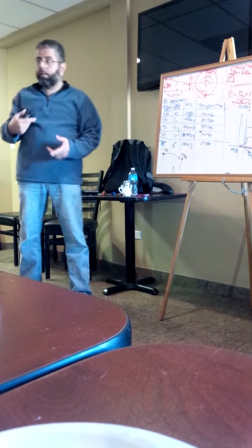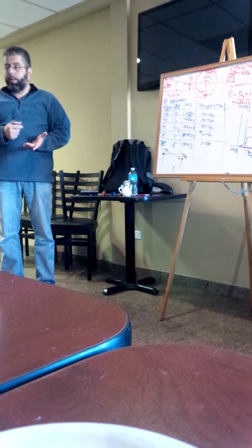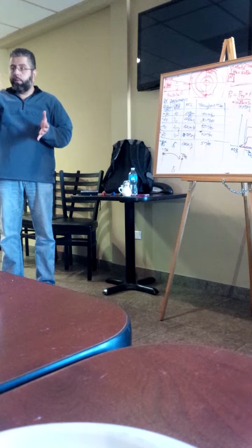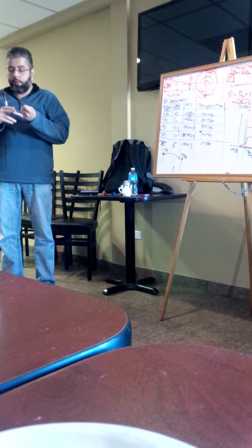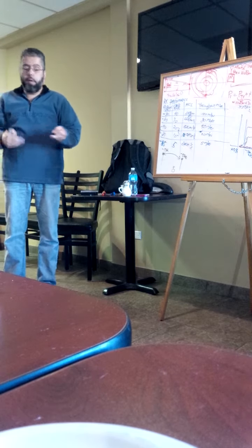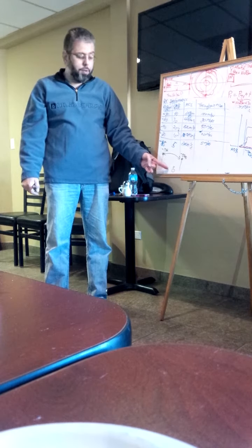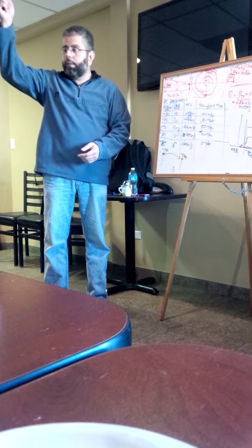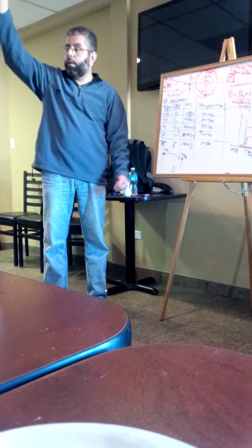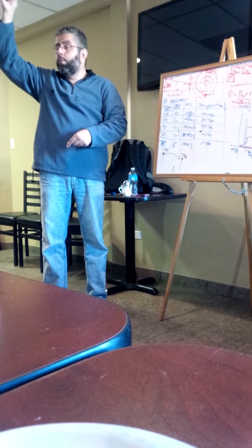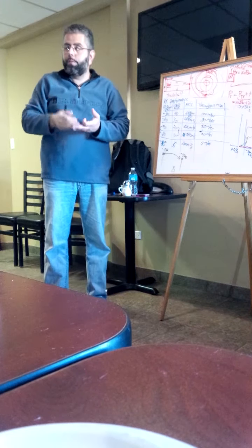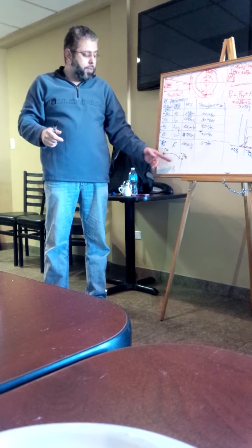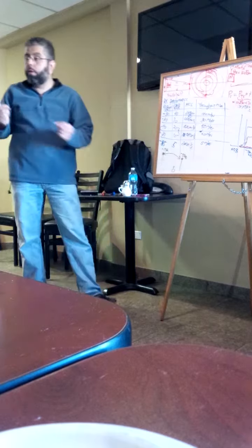The other problem with going down here is the antenna. If you use a different antenna, it has a different amount of gain, so it can't tell you exactly how much power you would see if you were using your antenna, unless you know how much gain is in your antenna and how much gain is in the antenna of the device you're using for the spectrum analysis. You can do it, it just needs a little bit more skill. And then you can also put your testing antenna on a pole and run a cable. The problem with running cables is that cables have loss. They introduce some noise, other noise figure problems for the sensitivity of the spectrum analyzer you're using. It's best to do spectrum analysis on those devices from the device itself.